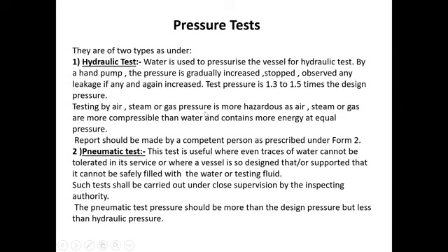In the pneumatic test, the testing is done by air, steam or gas pressure. It is more hazardous, as air, steam or gas are more compressible than water and contain more energy at equal pressures. So this is dangerous, and that is why competent persons generally prefer the hydraulic test. After the test, whatever format is given by the referred standard or rule, the competent person gives the test report in the prescribed format.